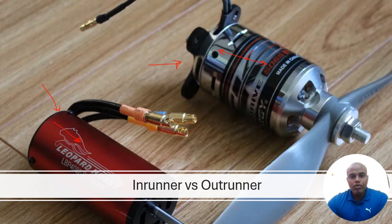Specifically, I just want to draw your attention over here. In the in-runner motor, these are the ducts over here. The stator winding is the outer part, and inside we have the rotor. Whereas here the rotor is placed so that it surrounds my stator winding. Whenever my permanent magnet rotor moves over here in the outer periphery, my stator is placed inside the rotor.